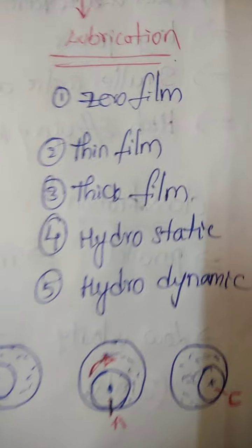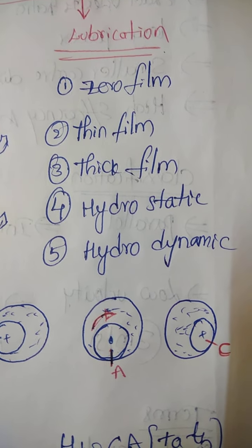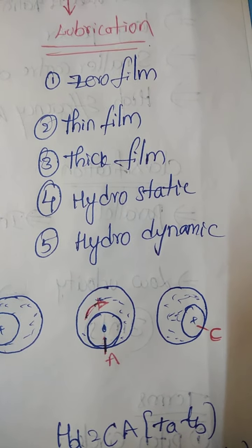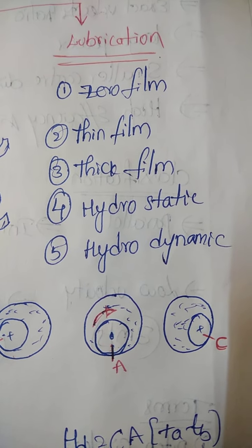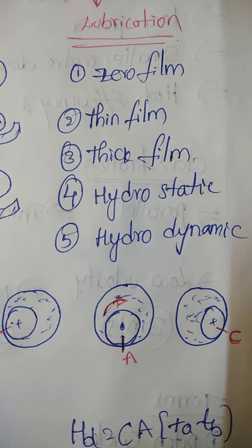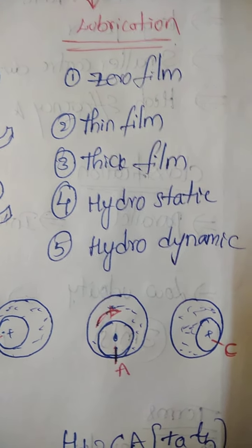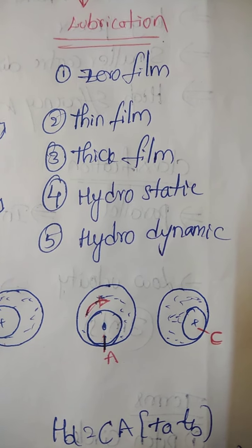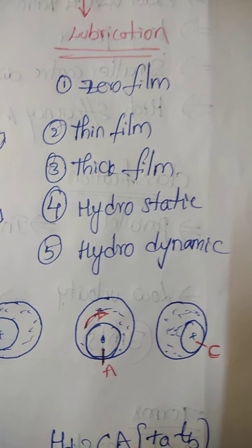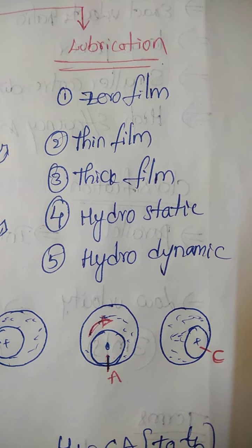Next, based on lubrication. What is the necessity of lubrication? In most cases the bearing is manufactured with materials like cast iron and babbitt material, that is, metals. When the bearing is rotating, there is metal to metal contact, so heat will be produced due to the frictional force. If you are not using any lubricant, the bearing may fracture due to this temperature effect, right? Wear and tear will occur, and the bearing may expand in a manner that causes defects in assembly. Then we go for lubrication.